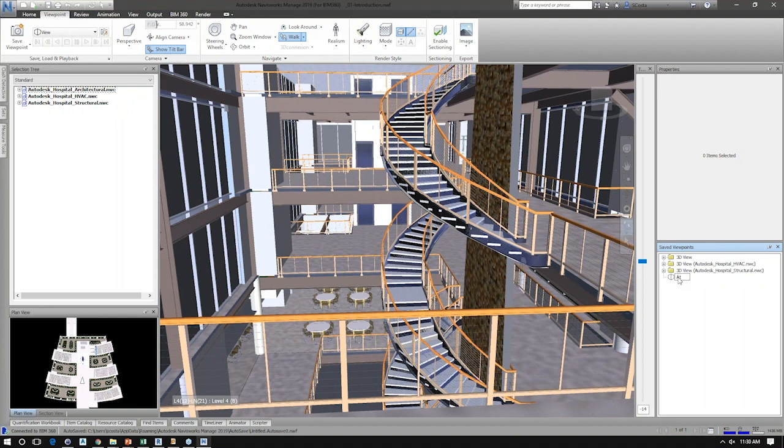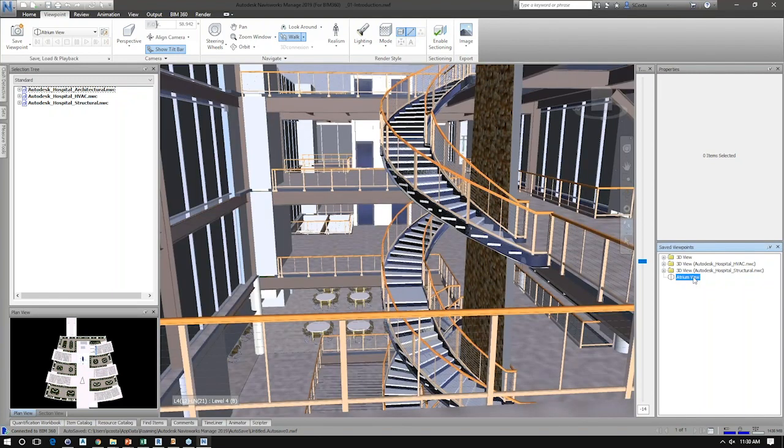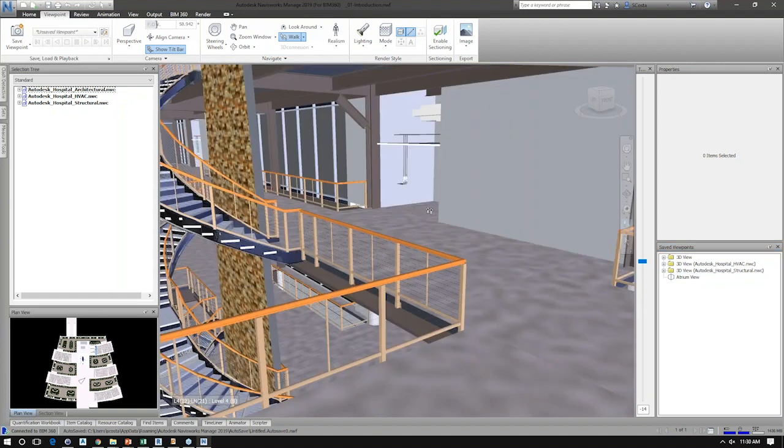And the nice thing is if I manipulate my tools to walk out of that and I want to go back to that view, I just simply select that view and I'm back, or I should say that viewpoint. So viewpoints will store any of the views that were created inside of the Revit project, as well as any of the ones that you're going to want to create for yourselves to set some viewpoints so that you can go and show the project off to either a coordination team or a client